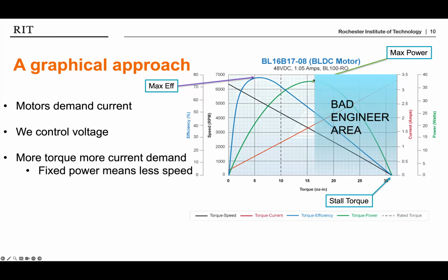And you might kind of squint and go, that's not what I saw in class. Well, actually it is. The people selling the motor just kind of knew that you were a good enough engineer not to pick a design point over here. All right, that is another nice, important thing, so rewind the video if you missed that: we do not design past our max power. And leave yourself some space if you're taking notes, because we're going to expand on this one more time.